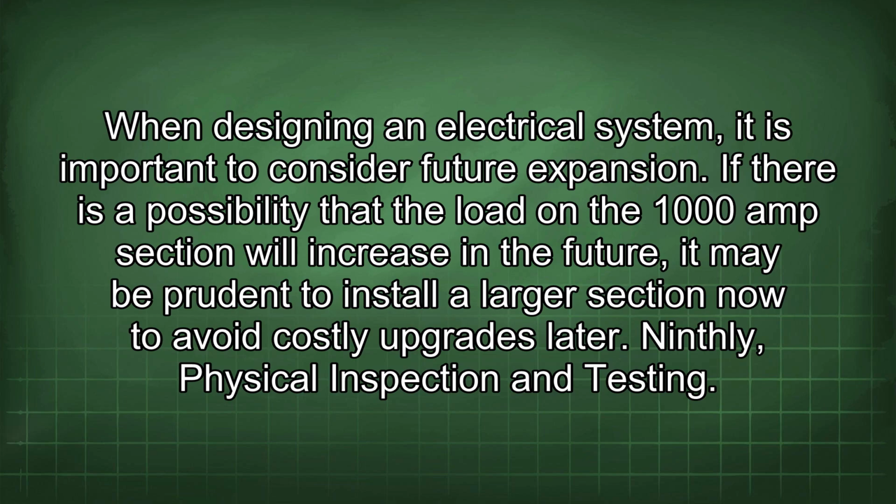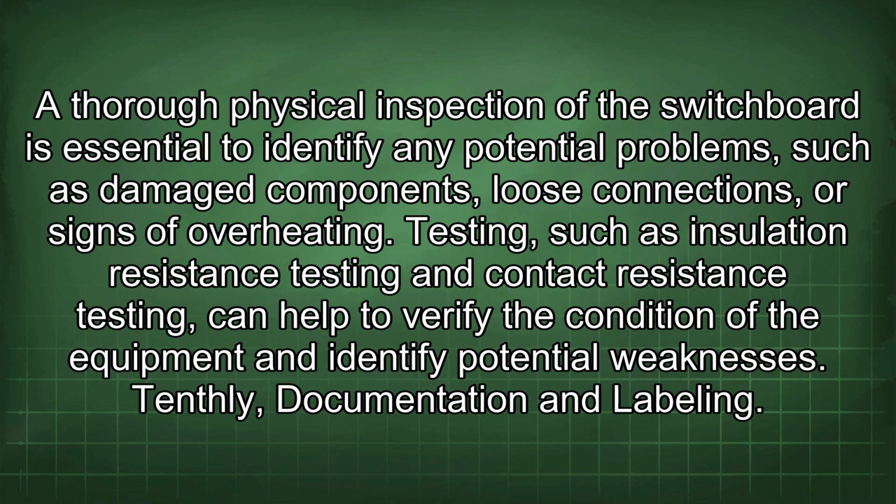Ninthly, physical inspection and testing. A thorough physical inspection of the switchboard is essential to identify any potential problems, such as damaged components, loose connections, or signs of overheating. Testing, such as insulation resistance testing and contact resistance testing, can help to verify the condition of the equipment and identify potential weaknesses.